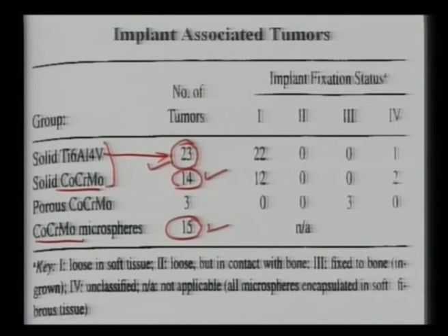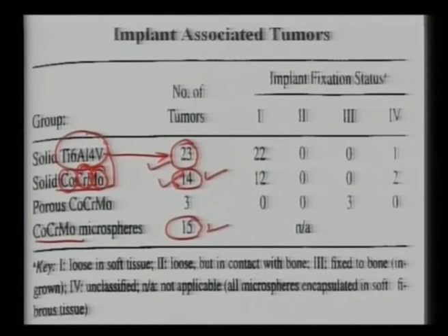However, when they are implanted inside the human body, their wear particles, containing cobalt, chromium or moly, can potentially cause a genotoxic effect when implanted for a longer duration, and therefore they also have a tendency to form a large number of tumors. That is the reason they need to be replaced with better materials. So although they have better mechanical properties, that does not mean they should be accepted for biomaterial applications.